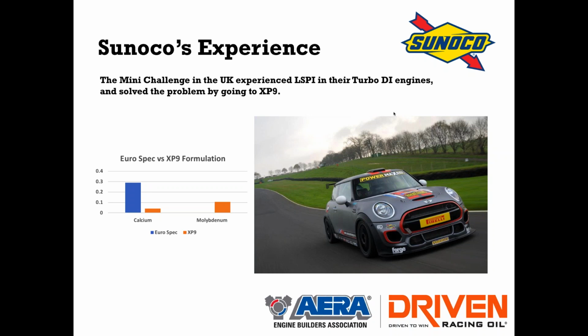And we said, okay, well, that's a problem. Let's do a real quick swap. Let's get you to a very low calcium oil that has a higher level of moly in it, which is a race oil. Got them the race oil and changed that detergent moly balance, and all the problems went away. So it was kind of a neat real-world test to see, okay, well, here's a problem where they're really having LSPI problems in the real world. Let's make this change chemistry-wise, and can it affect it? And the answer was yes, it certainly affected it.